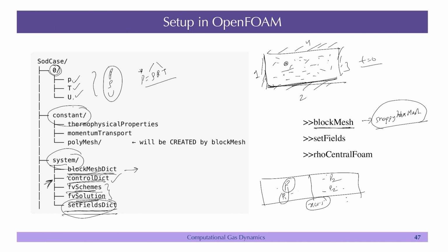want to, after you define or make your domain and the grid, specify some initial condition, some specific initial condition. Let us say you have a shock which is impinging on a wall, okay, and you want to start with this as the pre-shock condition and this as the post-shock condition, and you want to see how it develops, right. So, in the grid you have to specify all these things. So, those things can be set up using the setFieldsDict.